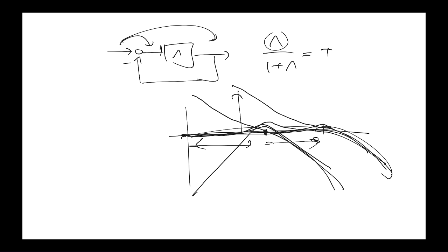So, yeah, we're just relying on the fact that there is this loose relationship between the crossover frequency and the bandwidth of the complementary sensitivity function. Of course, if the complementary sensitivity function ends up peaking like that because you've got not a very good phase margin, then really the range of signals that get through without attenuation, without distortion, is only up to here, right? So you probably wouldn't call that the bandwidth. You would call that the bandwidth. But if you've got better damping, then those numbers are close together.